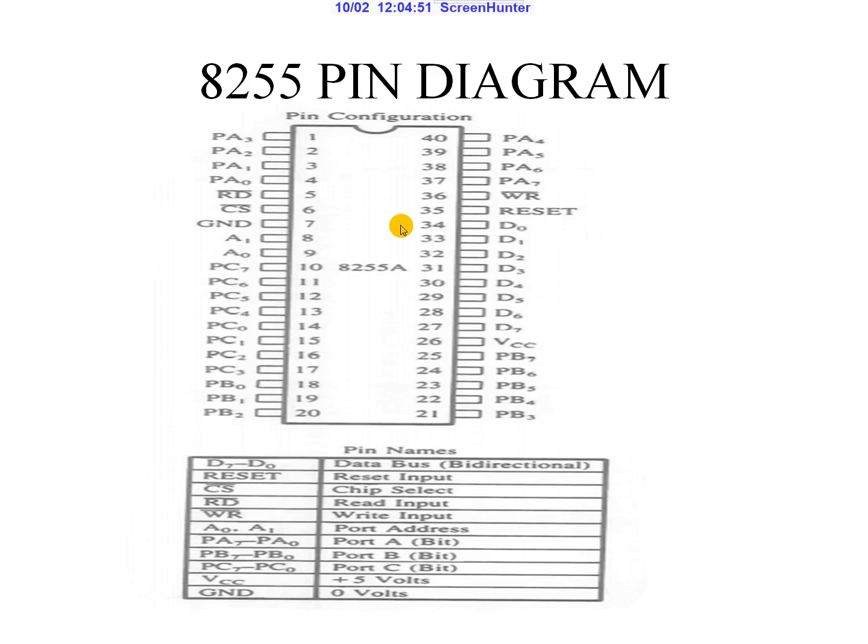Here you have three ports to be interfaced with the external devices and your microprocessors. Port A goes from PA0 to PA7, and port B goes from PB0 to PB7, and port C has two 4 pin ports.